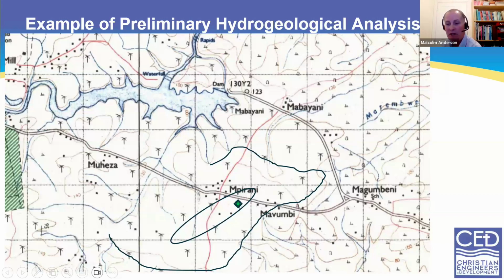Now that I've established my 2 levels, incidentally, the reason this one is this length is I'm just trying to keep contour distances between the 2 of them about the same width, because the groundwater flow will be roughly the same and therefore require roughly the same slope, and therefore you should get roughly the same geometry of the high to the previous contour I've picked out. So from that I can then put in the groundwater flow directions to each of the streams.